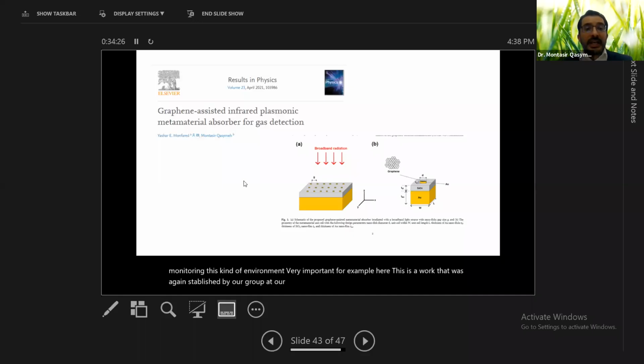We have designed a gas sensor that is very sensitive, to measure different kinds of gases at very low concentrations. The principle is that we direct radiation, like laser radiation or near infrared radiation, or it could be broadband radiation, at a structure that we have designed. The absorption of this radiation in the structure depends very seriously on the gas that is surrounding it.